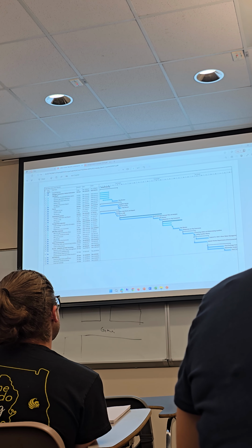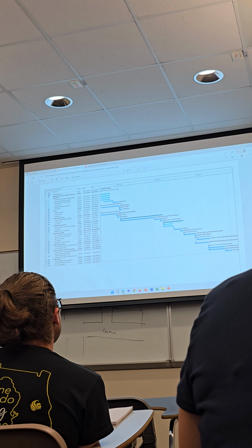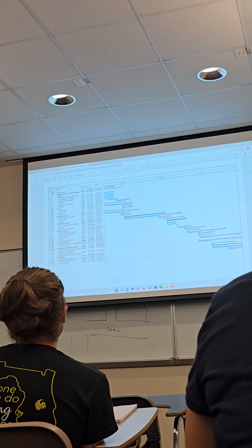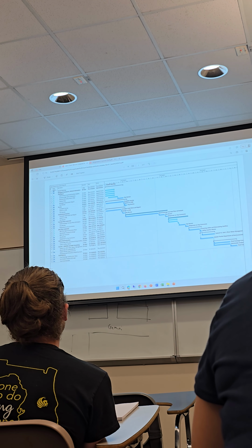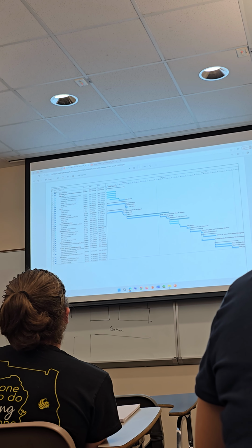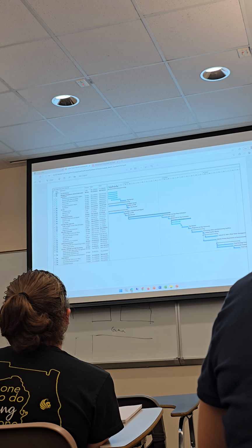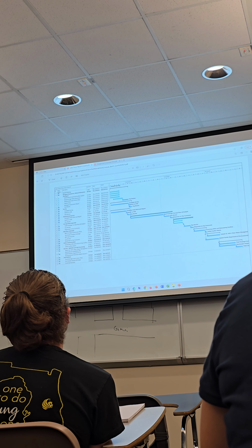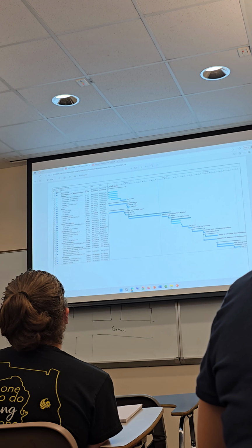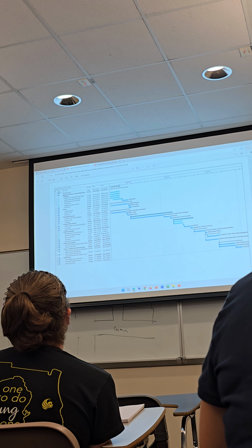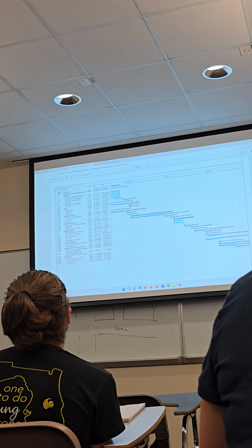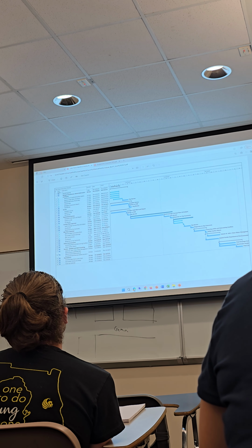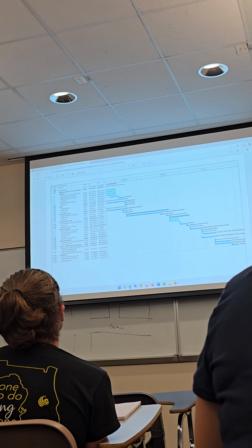And typically, when you're putting together a set of construction plans and you're going to apply for a permit, you would typically do that at a 60% or maybe a 50% design level. So you'd have your plans in pretty good shape. That's when you would submit for your permit applications. While those are being reviewed, you're working on getting to your final plans, and then you marry those up towards the end. So that's typically how that's done.